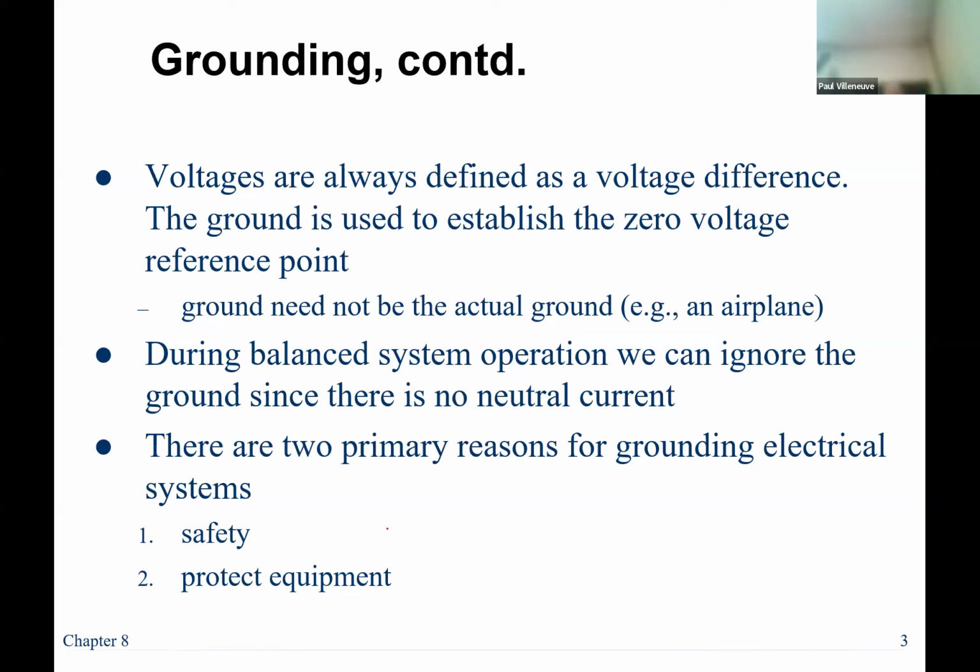So the reason for grounding is safety. It's way safer if you have a grounded system, because if a conductor comes into contact with ground, then that trips the breaker, as opposed to it starting a fire or anything like that. It also provides equipment protection too. So when you walk up to a piece of equipment, the case should be grounded. For those of you doing your senior project, if you have a metal case, you darn well better make sure it's grounded to what your circuit's at, because you could come up and touch it and you could electrocute yourself, right? You could provide that path.